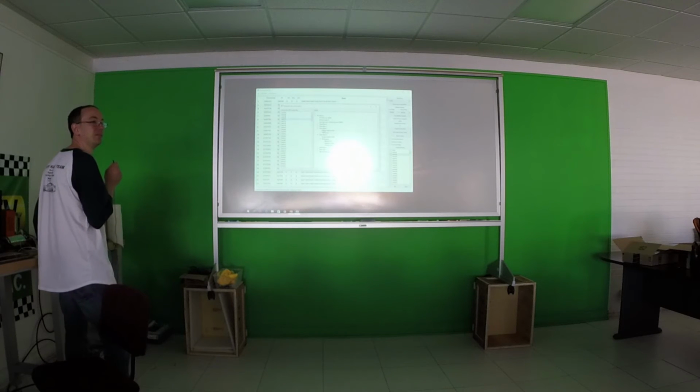If you have 100 millisecond frames, and you come across one that's being sent every 10 milliseconds, somebody did that for a reason. You don't want any delay. Can you sort that list by the interframe interval? No, you can't at the moment, though that might be a good idea. Also up here, you can see Jack mentioned how many messages are on the Tesla bus. It's 187 unique IDs in this capture.